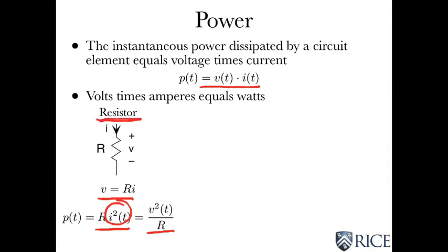And that's why the wattage of a resistor is very important to consider, because it's going to dissipate power, and you had better have a physical design for a resistor so it can let the power dissipate freely up to its stated rating, but always dissipate. So resistors dissipate power. So there has to be some other element in the circuit that produces the power that the resistors dissipate.